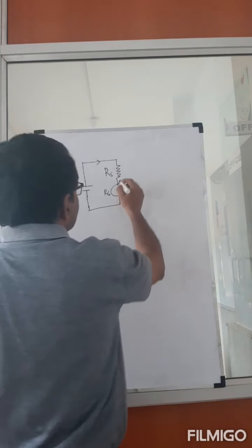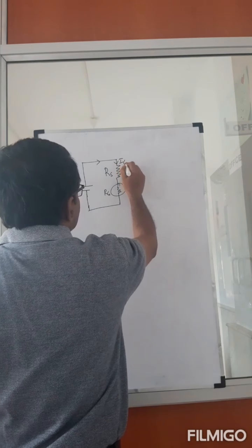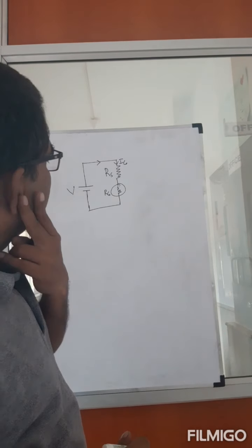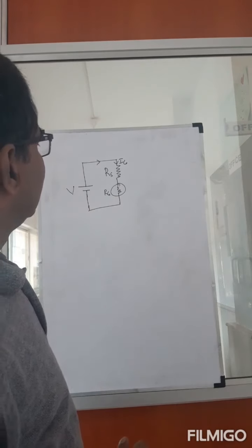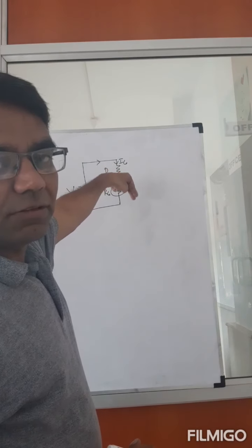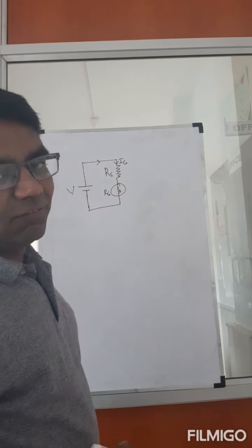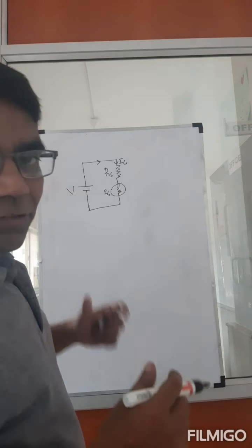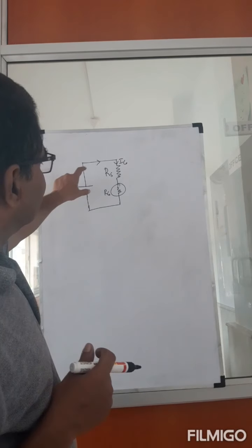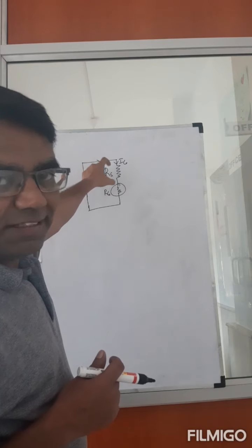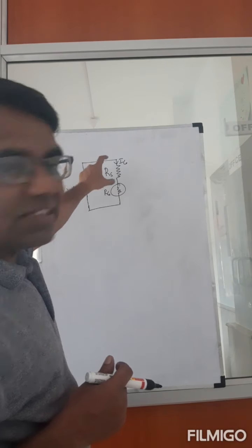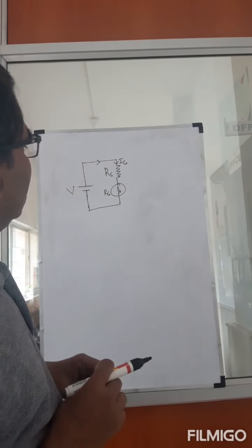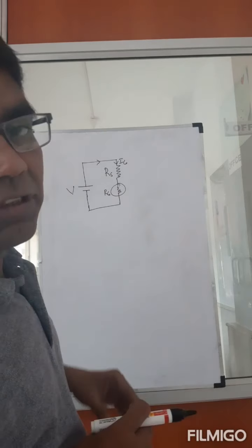So this is the galvanometer current, which I call Ig. The current which flows through the series resistance will also flow through the galvanometer. So this is the maximum allowed current to get full scale deflection. This is how you calculate the value of the series resistance we need to connect. The series resistance is used to limit the amount of current flowing through it.